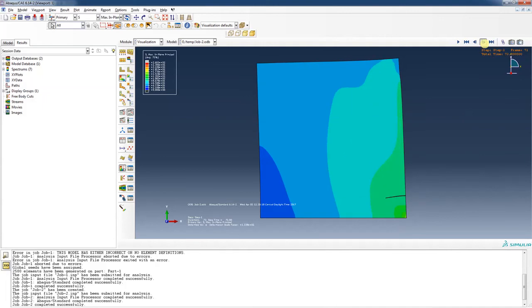from there. Now, how realistic is this? In a real material, it would be cracking down here where we've restrained it probably. So you might want to make a change in your component so that you have it larger over here, maybe thicker, and you have thinner over in this section, or maybe narrower so that you can control where that occurs. You may want to look at crack initiations near stress concentrations. Typically, cracks don't initiate in the interior of a component. Typically, it's a surface phenomenon. But it depends on how it's loaded.